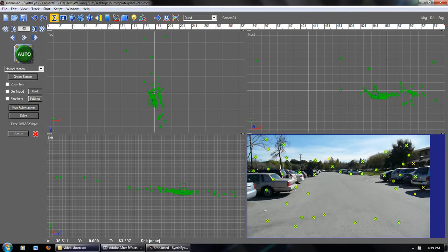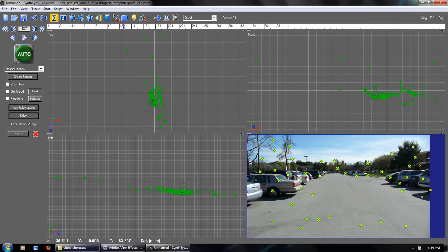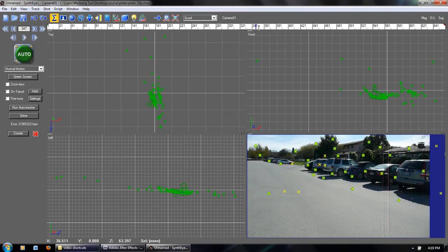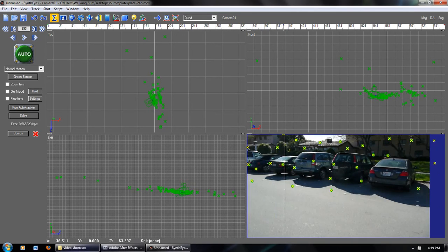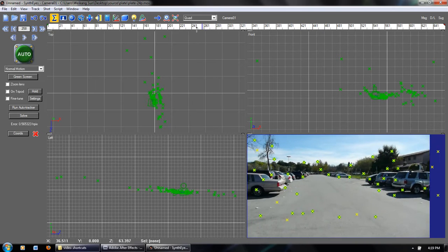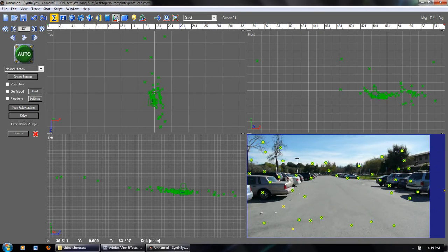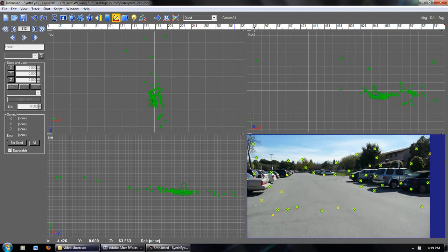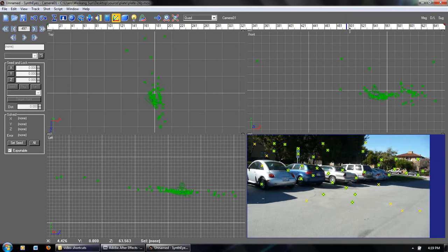We can go ahead and export this to After Effects, but what I like to do first is to define a set of axes for After Effects later, because right now the program doesn't know where the ground is or where the vertical direction is. So what I can do is click on this XYZ button, and click on this star 3 to define 3 points for my axes.